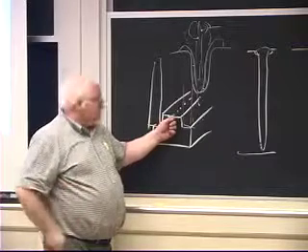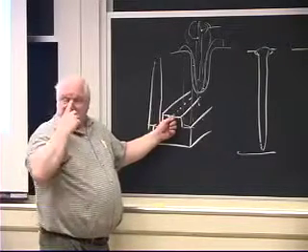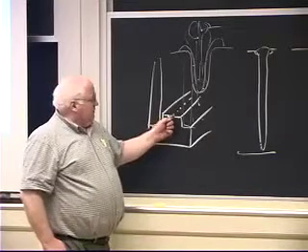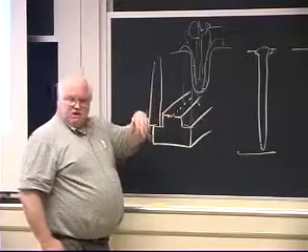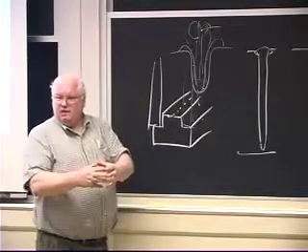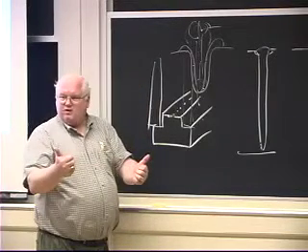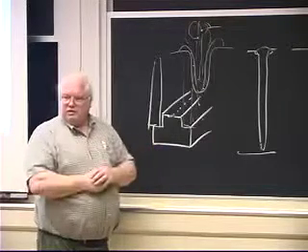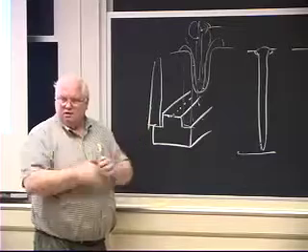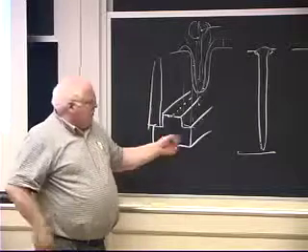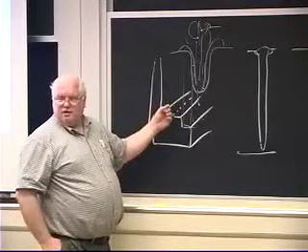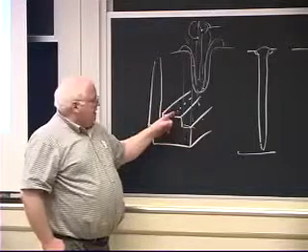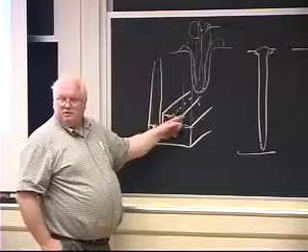a typical welding situation. So if it only has 10% efficiency for receiving the light, you put in 10 times the power density that you need, but then you get some surface depression, and now the laser light is going into a cavity, and in the cavity it's just re-radiating back to itself. Once you drill the hole a little bit, you're getting 10 to the 7th, which means you're blowing things apart, and you decouple with all that vapor that shoots out of there. You lose your beam, it spreads out everywhere, and then you recouple, decouple, recouple, decouple.